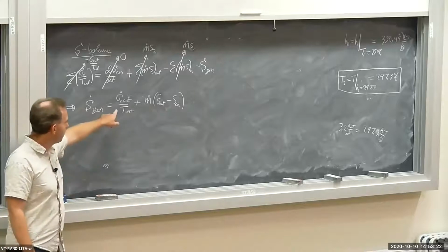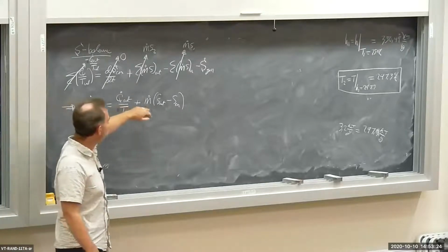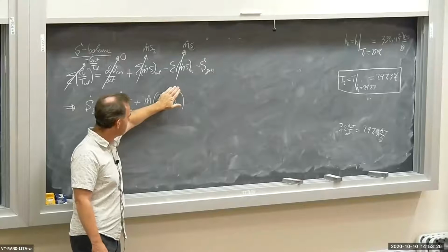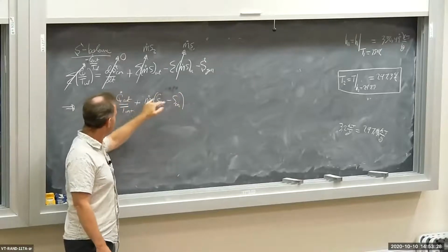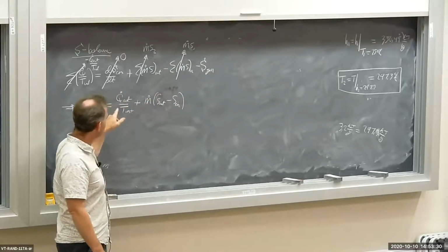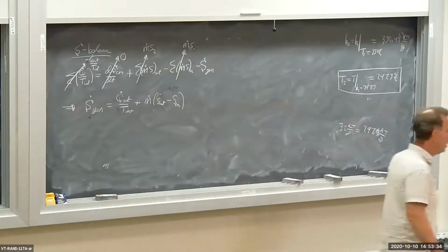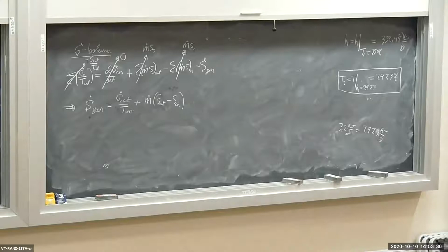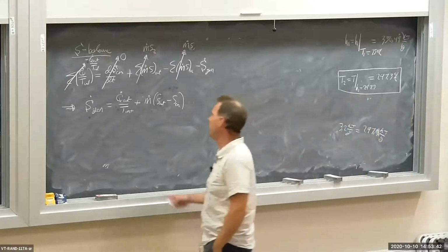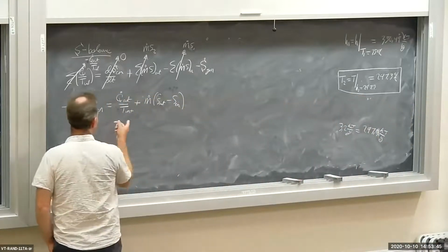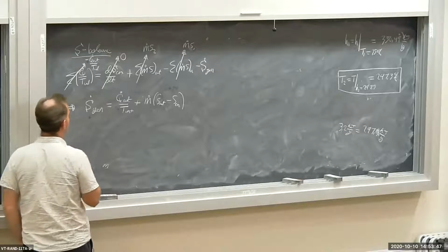Let's say there was no mass flow at all, so this term was gone. That means the rate of entropy generation is equal to the rate of entropy transfer out of the system due to the heat interaction. That makes sense. Okay, now this Q, we need to massage this a little bit more. Let's divide everything by m dot.